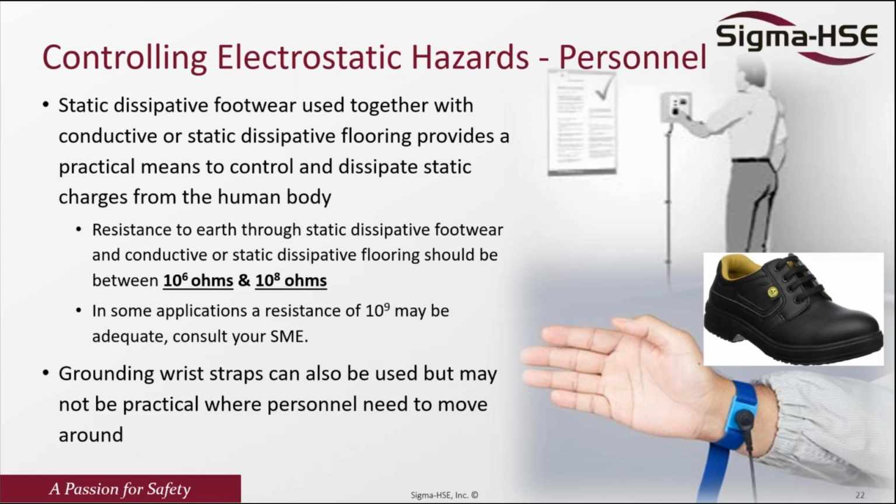Having the static dissipative shoe actually is not enough. You need to ensure that the flooring where you stand is also conductive. Normal cement is conductive, or you can paint it with a static dissipative material, or you can have a static dissipative mat. For ergonomic purposes, excellent. If I'm a worker who stands at one place, I'll tell you I need a static dissipative mat, which has a cushion and ergonomically it's really, really good.